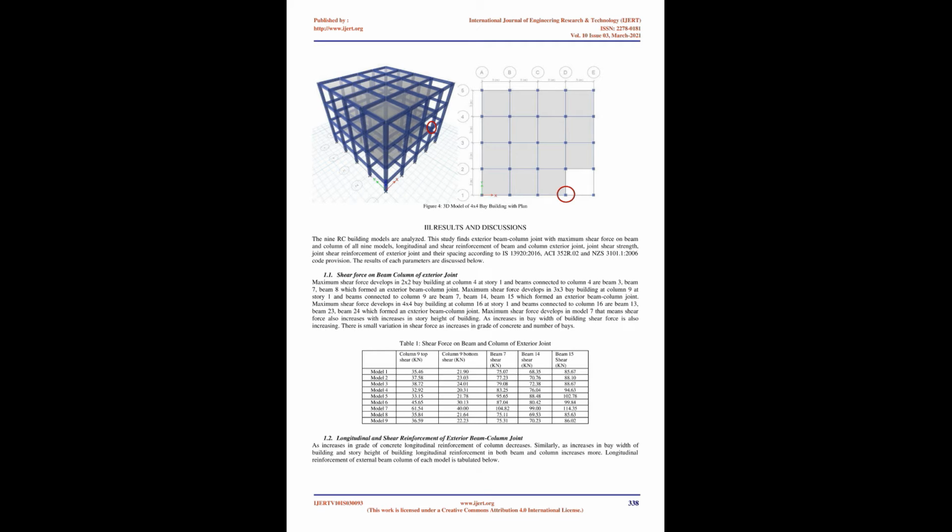Earthquake load, zone V, importance factor 1. Response reduction factor 5, soil type 2, mass source taken from IS 1893 part 1, 2002. Wall load, 230 mm thick brick wall of unit weight 18.85 kN/m3 from IS 875 part 1, reported by IS 875 part 1, 1987. Live load, 2 kN/m2 for all rooms and 1.6 kN/m2 for roof, taken from IS 875 part 2, 1987.